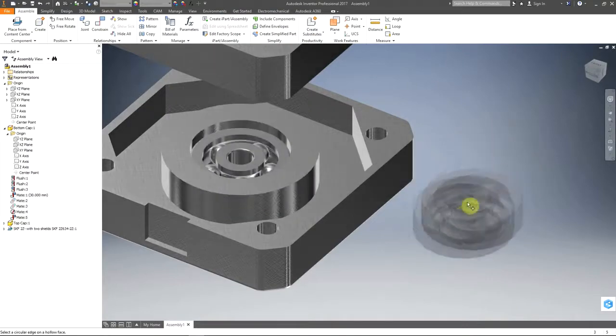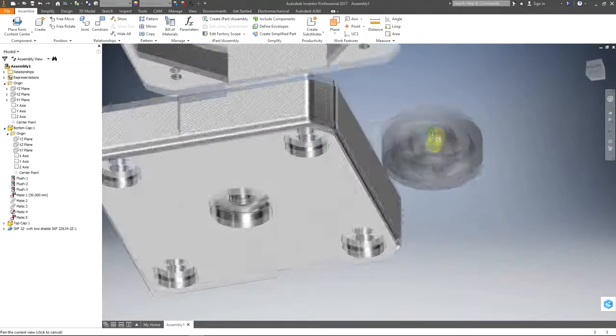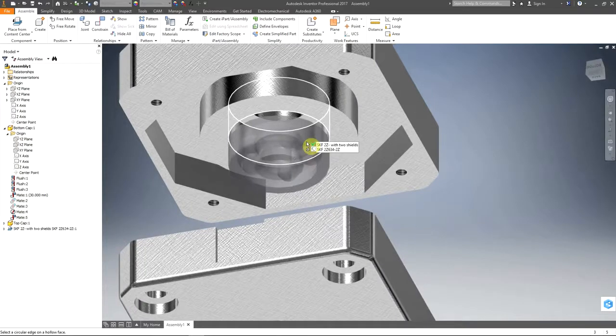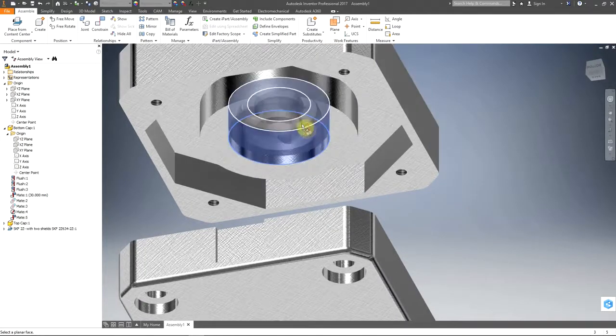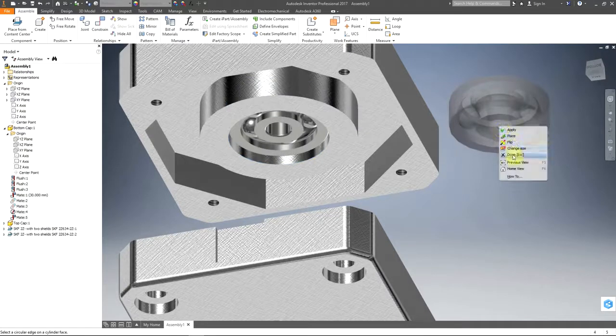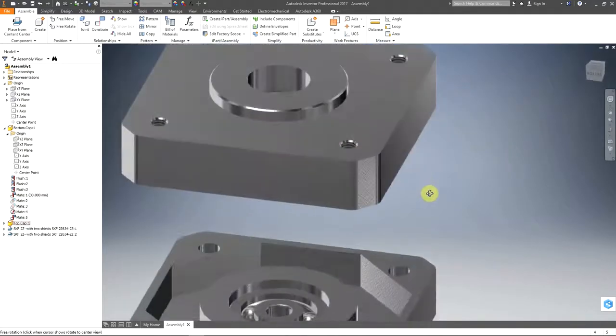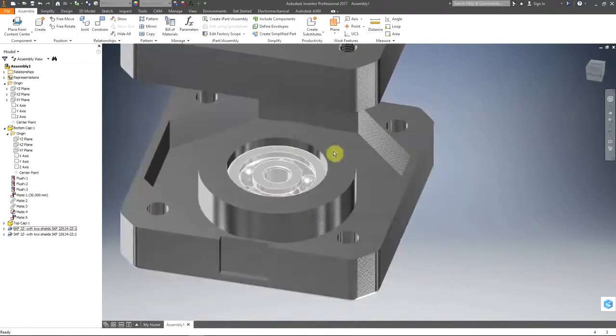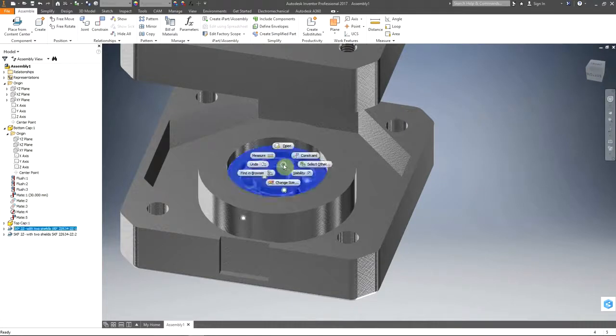All right, now we're going to do the same thing for the top face. So surface, surface, tick. Right click, done. Alright, now notice when we put them in there, we've got a 16 mil diameter, but we don't know what the inside diameter is. The way we fix that up is just right click on one of them and go to change size.